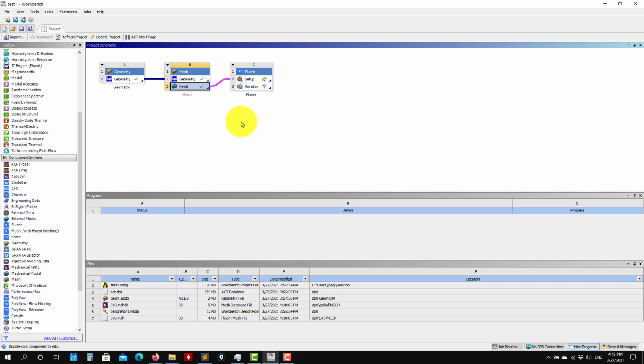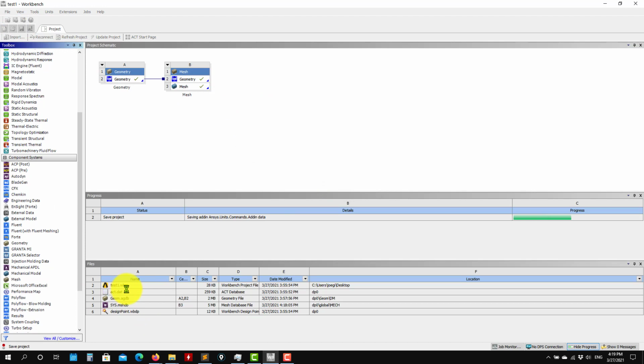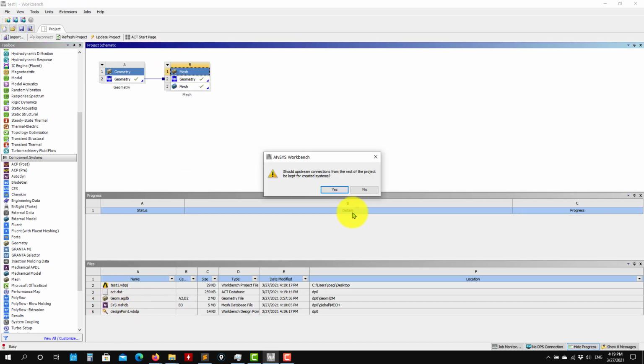So we have the mesh in Fluent. So let's say that now we want to create a second mesh. Okay, so I'm not going to run the case. Let me erase here. Okay, use erase. Okay, so see that the mesh was erased, and let me duplicate this one. So it is duplicating what we have done.